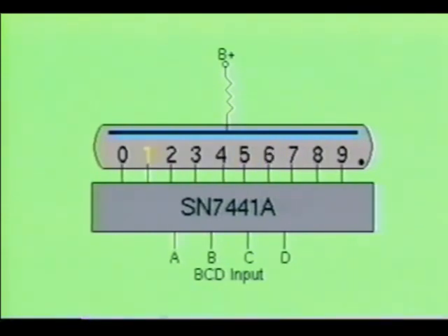The outputs are designed to drive gas-filled Nixie display tubes. The output voltage of this device will typically be 70 volts with a supply current of 36 milliamps. When in operation, the correct filaments are energized, causing the neon gas around the filament to glow.